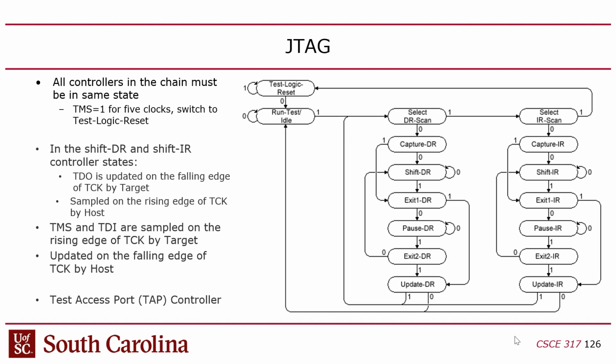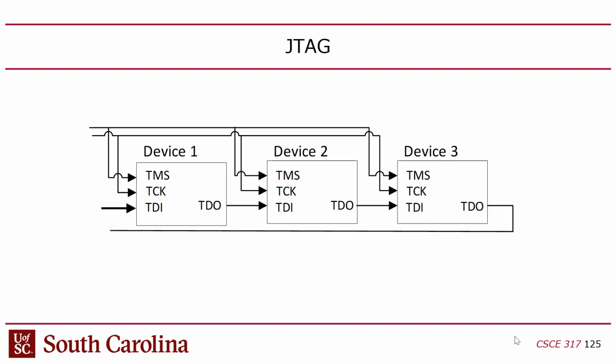And this is a synchronous protocol, so I provide the clock too. That's the nice thing. So I can even determine how fast I change states because it depends on how fast I drive the clock, right? Now once I'm in a state, then it's very simple. You've just got a big shift register. You've got data in, data out. So bits are just shifted through the whole chain. So the more devices on the chain, the more cycles I have to shift bits in, right?